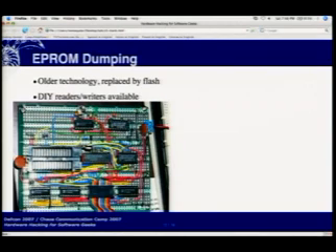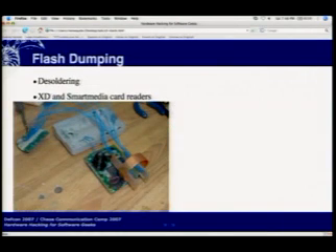Another thing where resources from the embedded engineering or forward engineering process come in handy is when you've got a decompiled binary. So the first thing you look for are vectors that are defined in the chip spec, like the reset vectors and the interrupt table vectors, and figure out where the code starts and where it goes when it jumps from the code it's executing to an interrupt, and then back. The first interrupt that's going to get serviced when the chip starts up is the reset interrupt vector. If you can find out where that is, that's the entry point for your code. You just tell IDA this is the entry point and it'll figure it out. Exactly, the G spot as it were.